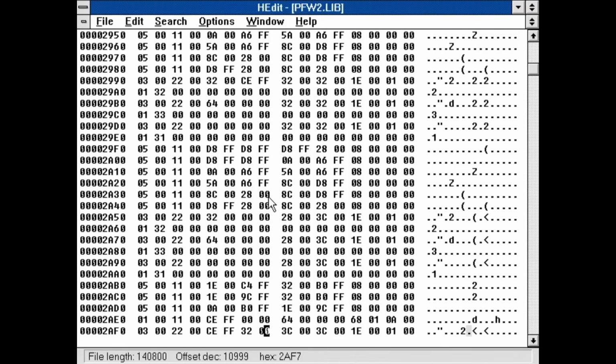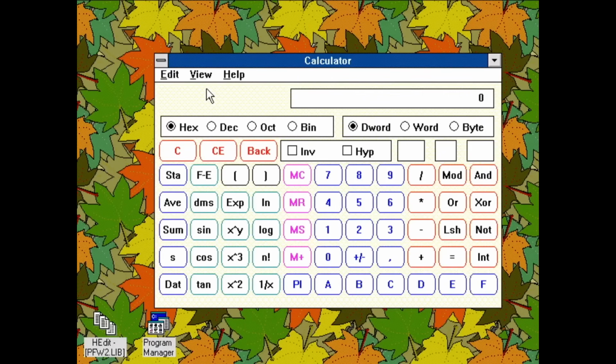I started out by just copying an existing component and modified that, but by the end of it I was able to write them from scratch. There was a lot of converting between decimal and hex, as well as from millimeters to thou, but that was pretty much the only tedious part of it. Aside from that, it wasn't much worse than making schematic symbols for EEDraw.